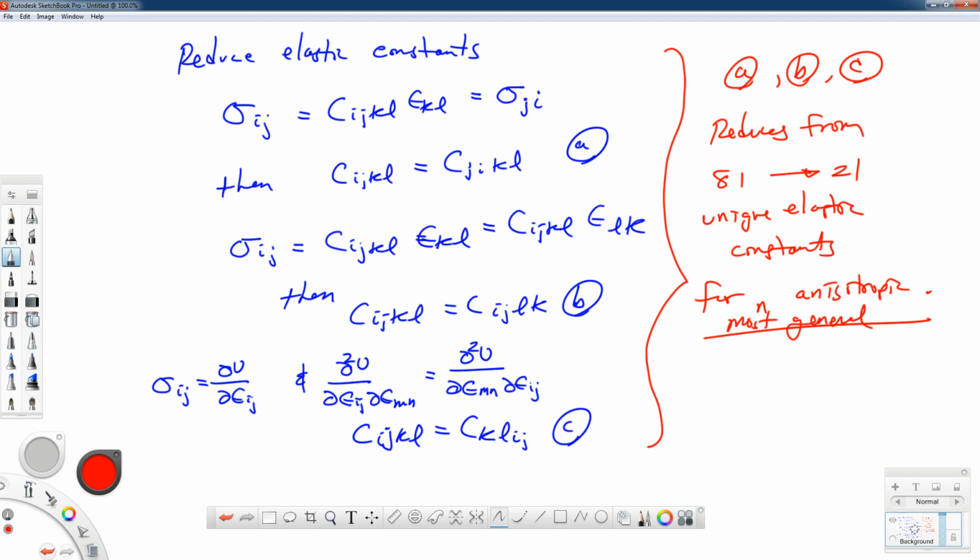Alright, so we've taken a look at material science notation in tensor notation. What we can do next is to see how this all works out to give a tensor form of Hooke's law. We can see how easy it is to invert Hooke's law in this case, which isn't really easy in the traditional way that we'd write 3D Hooke's law for isotropic materials. And we can find out exactly how our Lamé coefficients relate to our more familiar elastic constants E, G, and nu that we have for different isotropic materials that we would typically learn in our undergraduate mechanics of materials class.